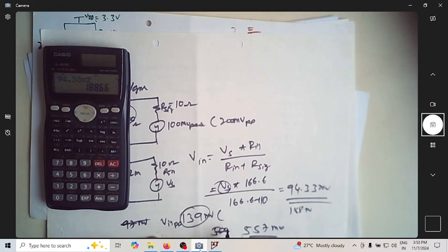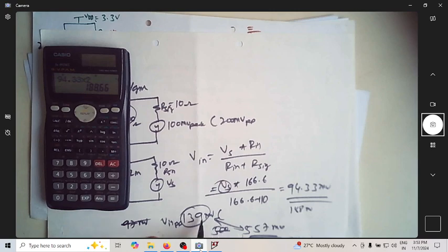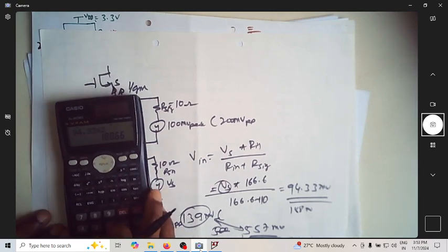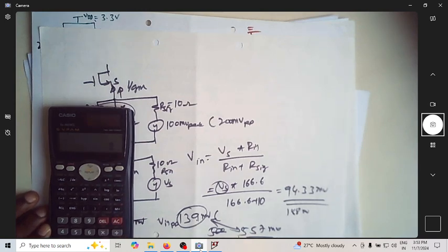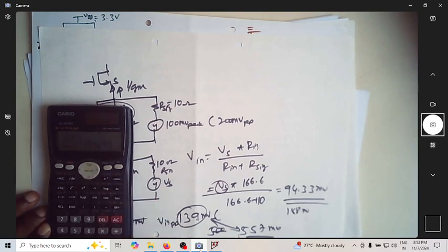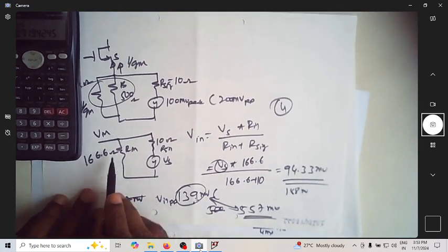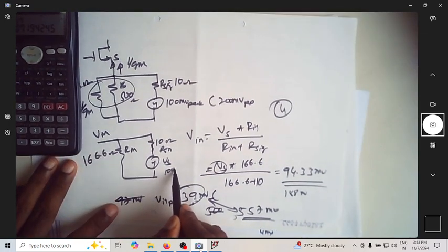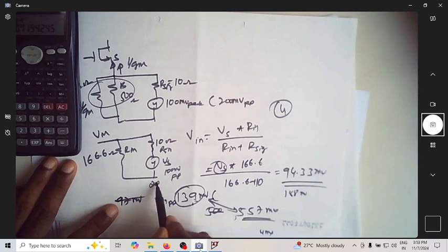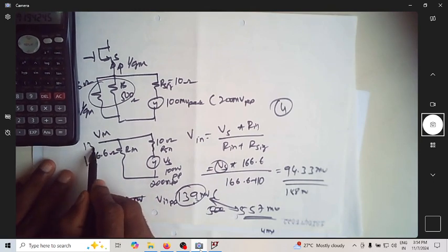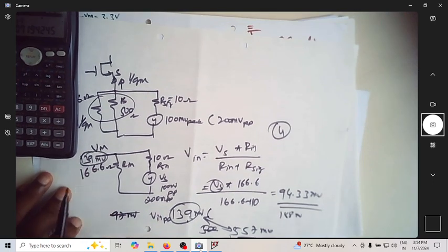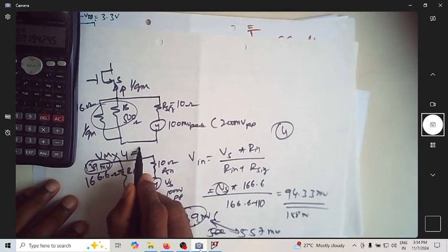That is fine. If you see the gain of this and this, this is the input voltage you applied and this is the output voltage you got. It is 557 divided by 139, which is close to 4. Out of 100 millivolt peak or 200 millivolt peak to peak, you are getting close to 139 millivolt as the signal that is available to the amplifier. This is amplified by 4 times.